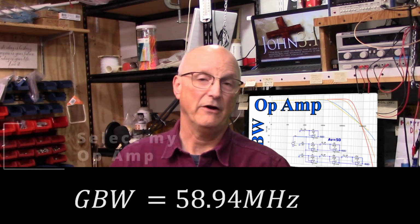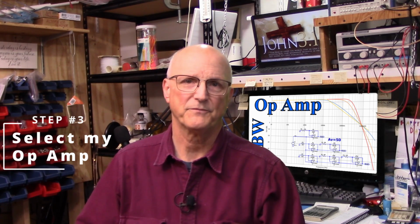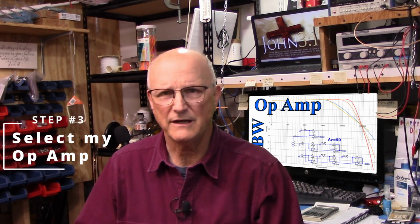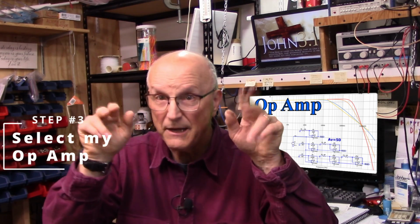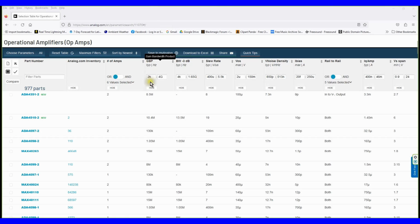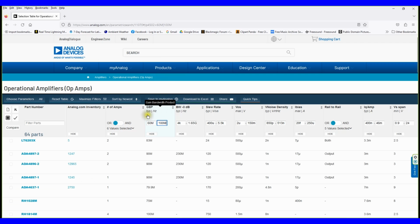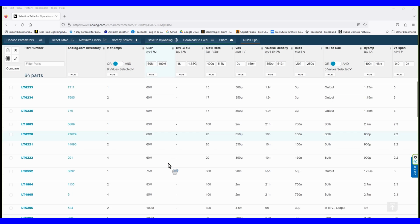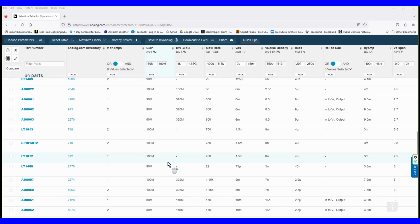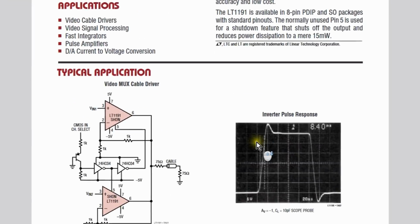Now I go out to the Analog Semiconductor website and use their parametric selector. I have to look at a few data sheets because they list the typical gain bandwidth product in the selector guide. I want to be sure that my selection is based on the minimum GBW, which only shows up on the data sheet, well, if they give it at all. Looking for this information on these data sheets can be quite difficult, and unfortunately, everyone seems to present these facts differently.